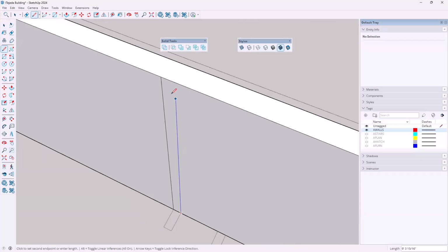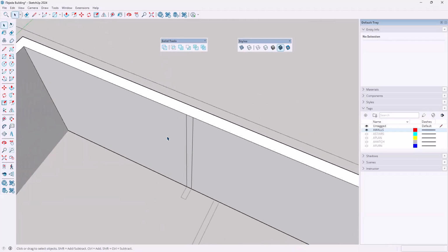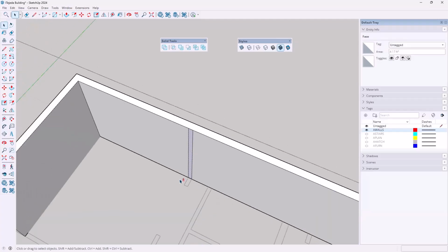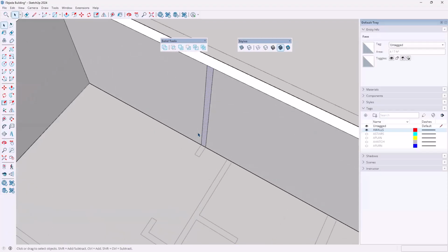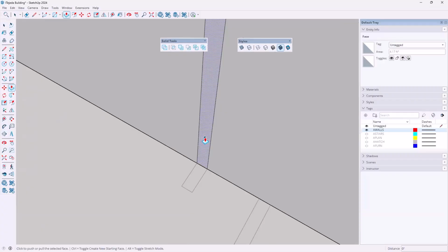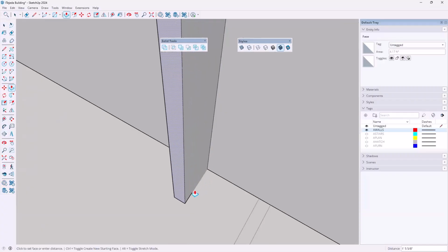And it looks like it is locking into the blue axis, but just to be sure, I use my up arrow key, and then I'll let it pick anywhere constrained on that intersection. Now, tap the space bar. What I've done is I basically have split that one surface into three surfaces here. I'm going to pick this surface, and then I'm going to type P for push pull. I'm going to push pull, take it from the middle here, or that area. I'm going to push pull it to the edge.